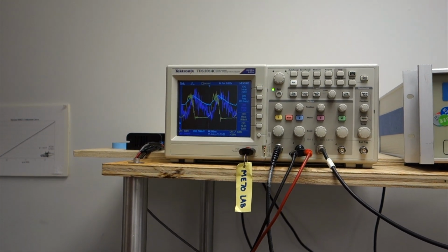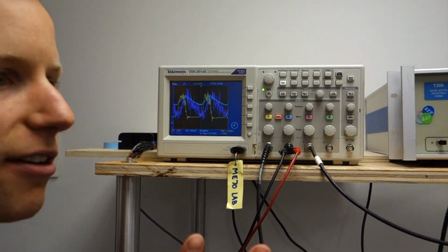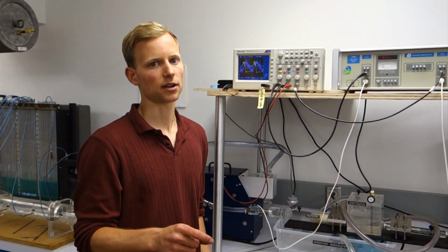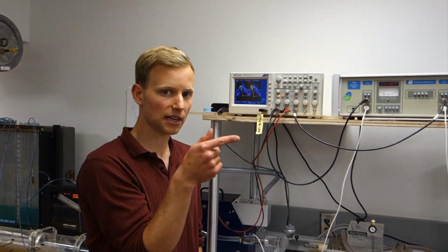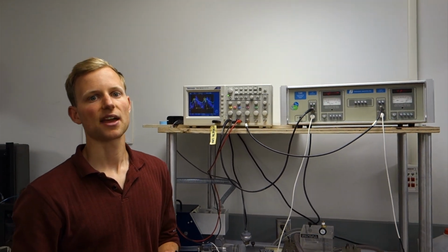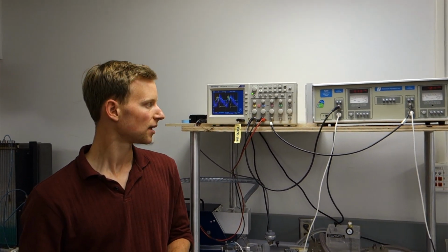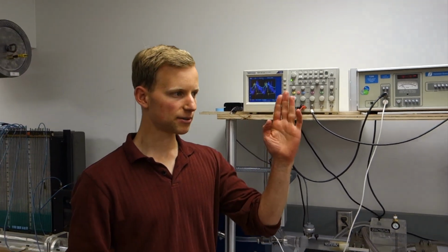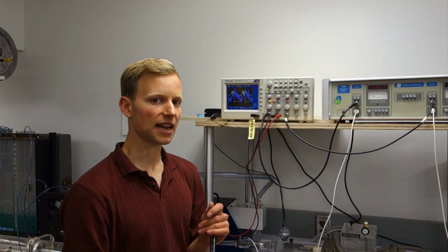It takes a minute to save to the USB stick, and what it's going to do is save 3 Excel files. They're going to be named some gibberish, and then CH1, CH2, CH3 accordingly. Our MATLAB script requires file names that are called ch1, ch2, ch3 without the gibberish. So what we're going to do is input this data by lopping off the initial gibberish characters, and then MATLAB will import the rest for us automatically. Each channel will have two columns, a time column and a voltage column. Then we can use the calibration, the transfer functions that we've talked about before, to convert those voltages into flow rates and pressure.